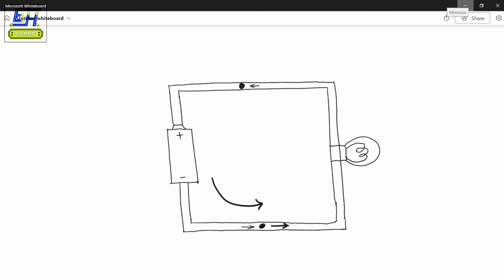So let's see then what is the mechanism of energy transfer from the source to the load. When we connect the energy source in the circuit, in this case the battery, we see that the electrical charges almost instantaneously build up and extend over the conductor as surface charge. On the positive side of the battery, you will see positive charge getting built up, whereas on the negative side, you'll see negative surface charge all along the length of the conductor. The remarkable thing is that this is almost instantaneous, limited by the speed of light in air, obviously, where this experimentation is carried out.